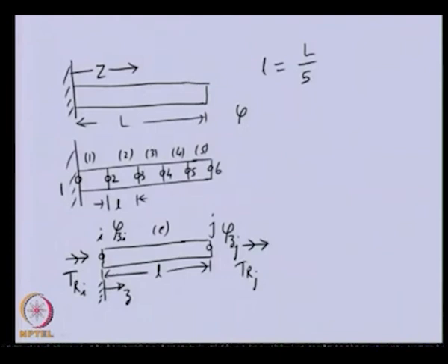So, this is the angular displacement of an element. Superscript E represents that this is the angular displacement for one element, which is a function of both axial position and time. We will be representing this as a polynomial. The polynomial will have some constants like a, b z plus c z square. We can take several terms depending upon the problem.